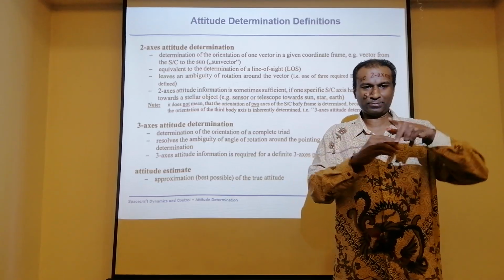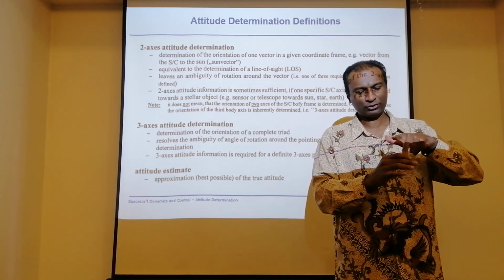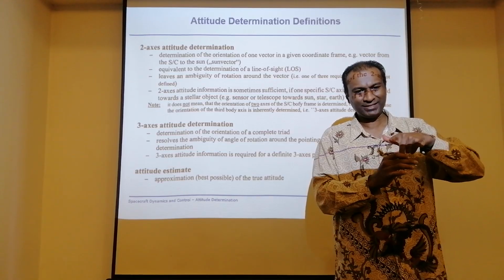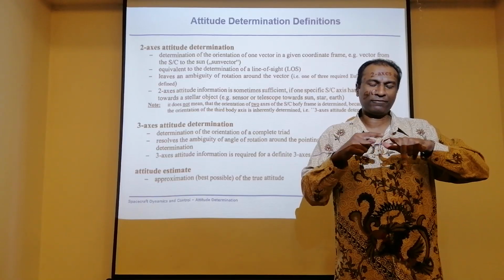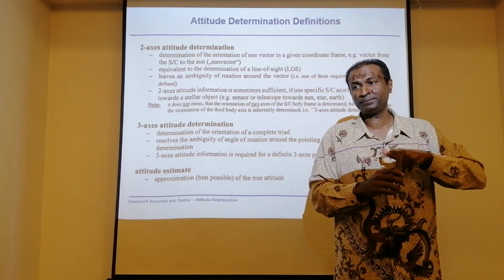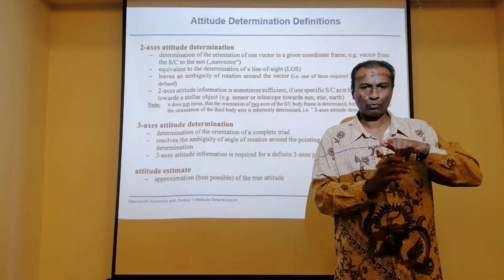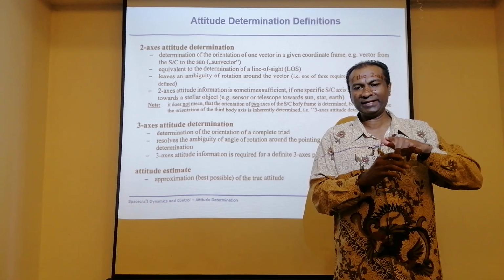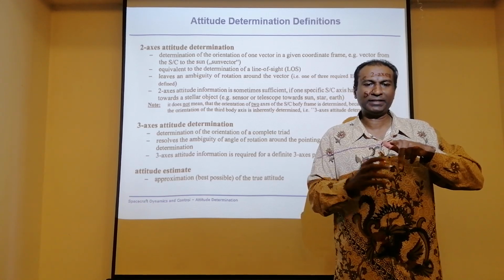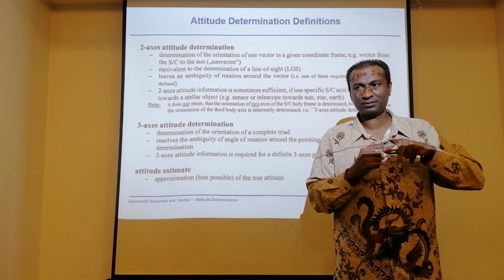Assume this has been tilted. Practically, this tilting is going to affect another two axes because they are orthogonal. So technically speaking, if I can sense this one axis, I should be able to tell that it has been tilted because there is some rotational motion in either both or one of the other two axes.